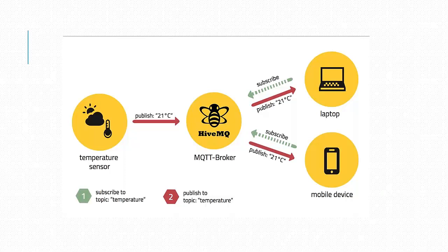Whenever we are going to choose any microcontroller, because we have AVR, ARM, different microcontrollers available in the market, we generally check the specification, what RAM we require, how many digital input output pins we require, how many PWM pins we require, and based on that we choose the board. It's not that we have only Arduino and the Raspberry Pi. We have lots of boards, and based on the requirements we choose the particular development board.